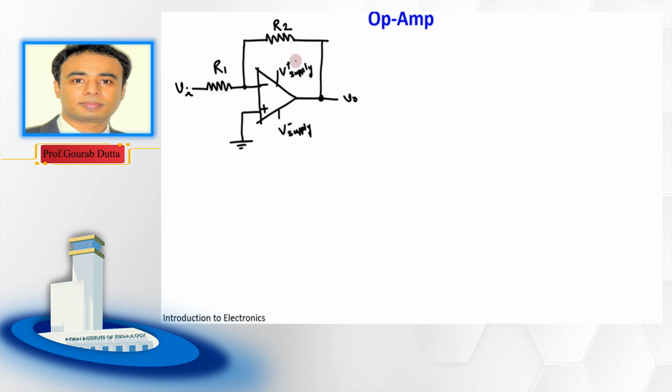So now tell me how to start the analysis for this circuit. What we are interested in is to find the gain for this total circuit, the input resistance, these things, right? Then how should we approach? Let us take two points here, say this point is point 1 and this point is point 2. So 2 is already grounded, right? But do we know what is the potential at this point 1?